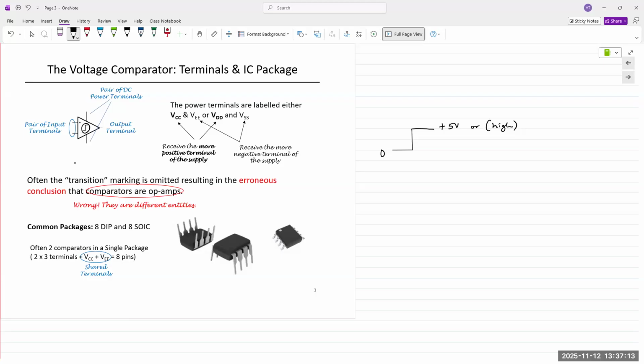That electrical signal is fed into a comparator. One end of the comparator is connected to the ambient temperature sensor. The other one is connected to our manual setting. And then depending on whether you choose heating or cooling, if it goes above or below the setting, that HVAC system would turn on or off.